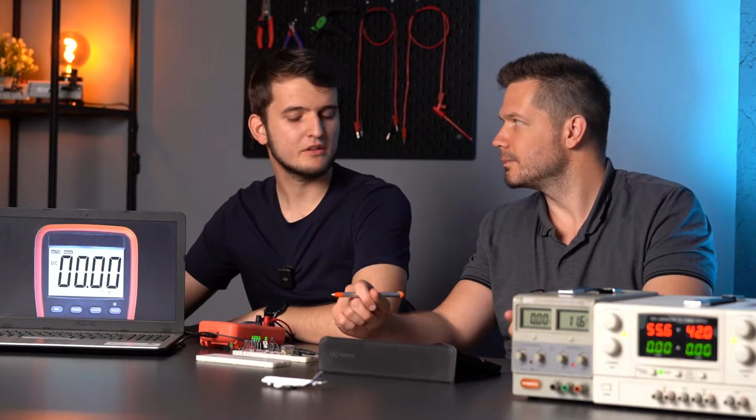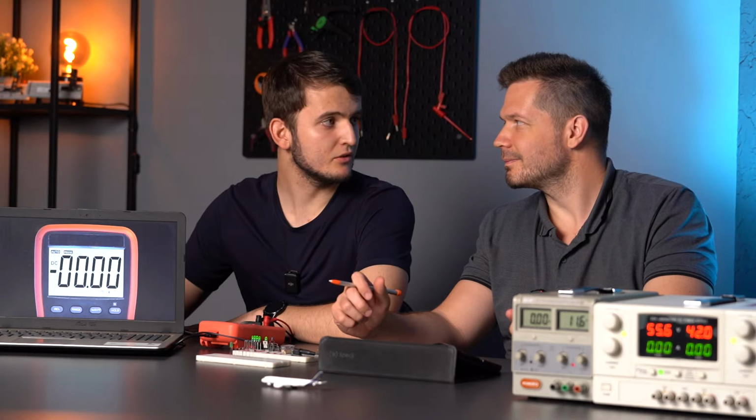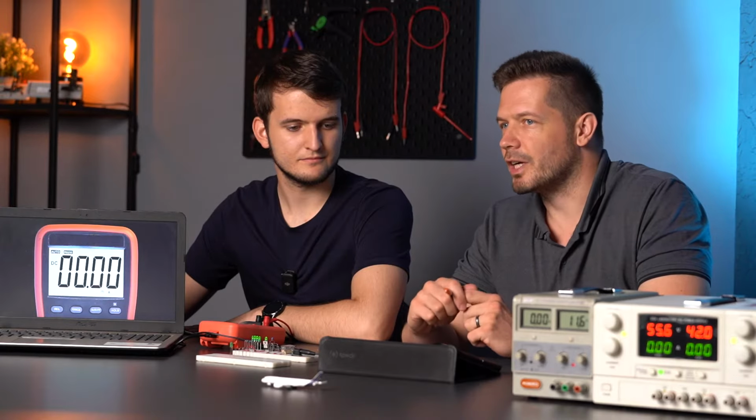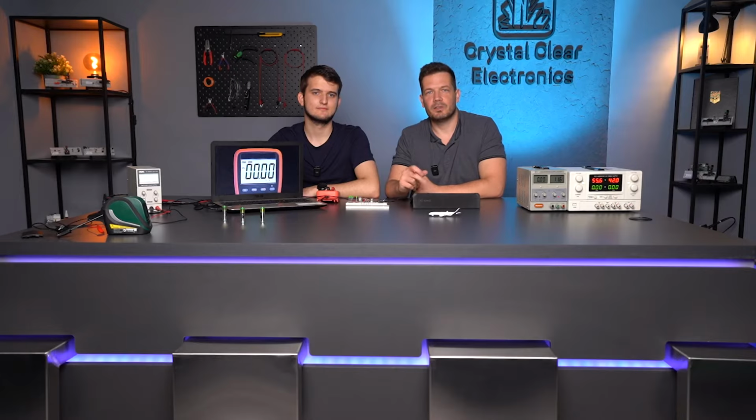Okay. And if the diode conducts, will it act like a normal resistor? Unfortunately not. A resistor behaves linearly, which means that if I apply twice the voltage to it, its current will be twice as high according to Ohm's law. However, the behavior of diodes in the open state is not so simple. This is where the so-called forward characteristics of diodes come into play.